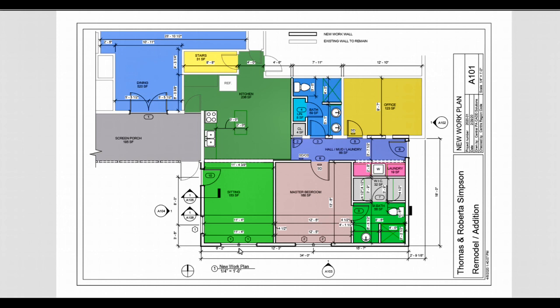So the dimensioning, this is a factory mulled window. I can see that note in the schedule, and I'm going to dimension to the center of that complete unit. So this isn't really two separate windows, it's one complete unit that I'm going to dimension to the center. So whenever I'm a contractor, I can basically measure from the outside corner, which does not include the siding. So that brings up a good point as far as how the dimensions, what they're showing.